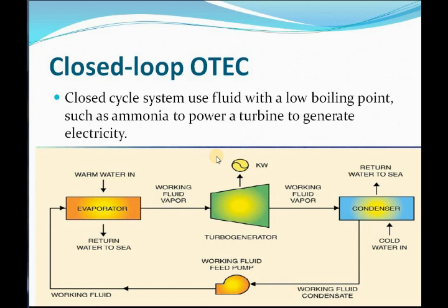In the closed cycle, I use a smaller amount of working fluid than in the open cycle, because of the operating pressure of the fluids we are using, the ammonia and propane and high Freon type refrigerants. The density of these working fluids is high.